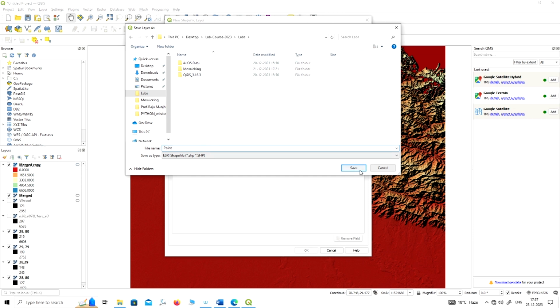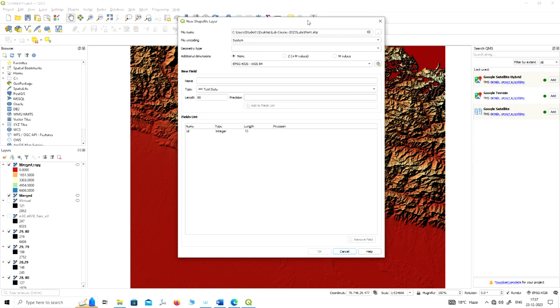and you save the file name, and then from the geometry type you have to assign which kind of shapefile you want to generate, either point, multi-point, line, or polygon. So first I will start with the point, and then you have to give the other information, for example, the reference system, for which coordinate system you want to apply on this point shapefile.